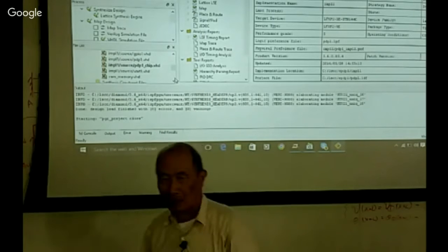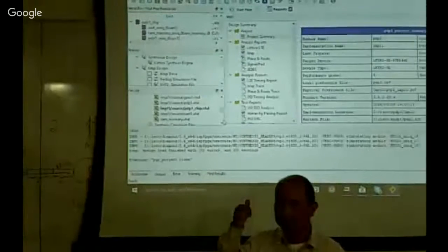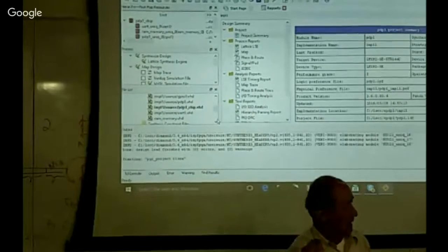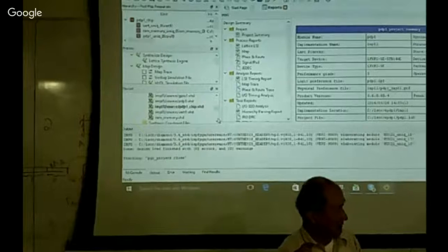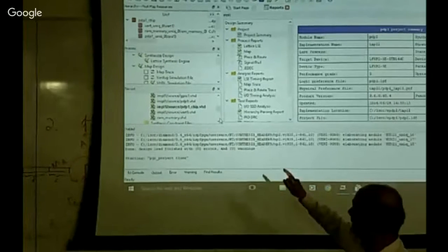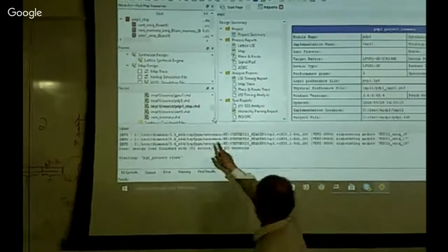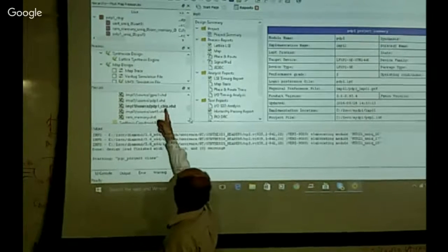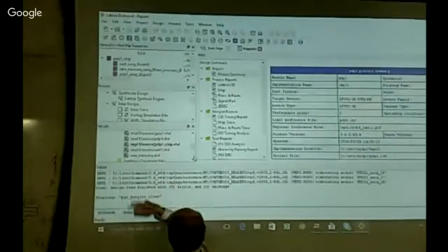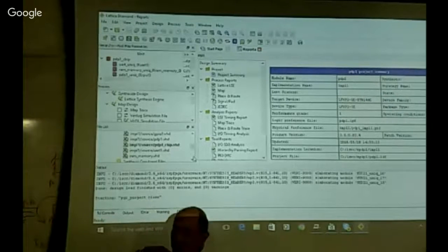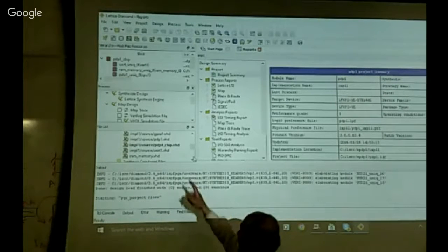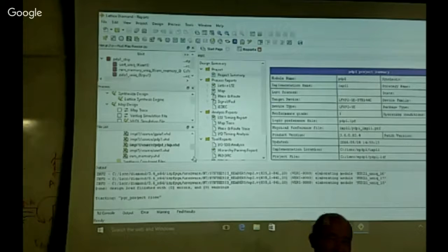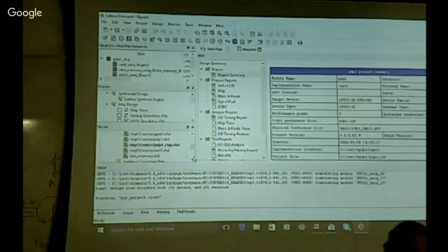With these exceptions, I was able to write my VHDL files. The top file, UART and GPIO don't need to be changed much, and only the CPU part needs to implement the new instructions. But there are not too many instructions.